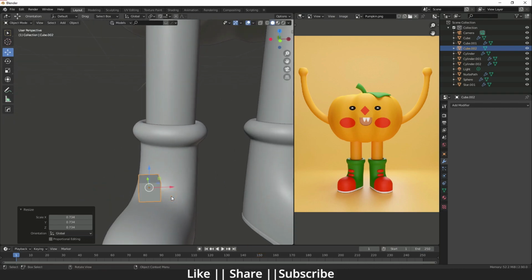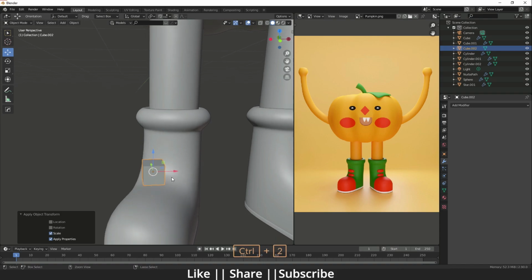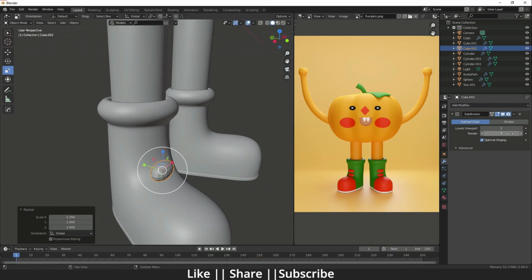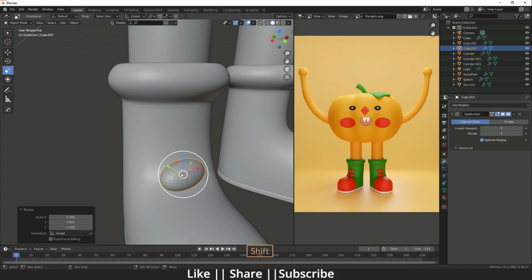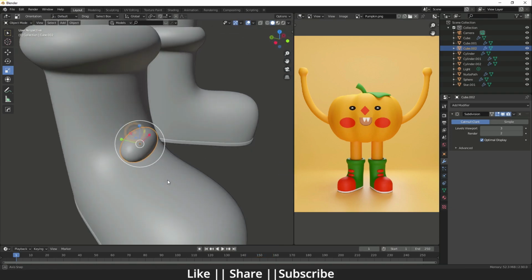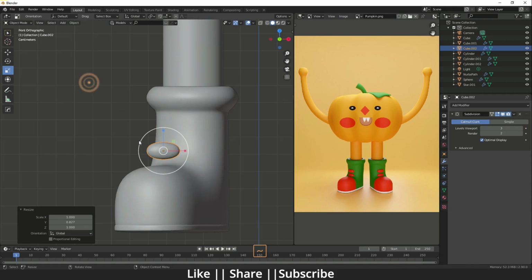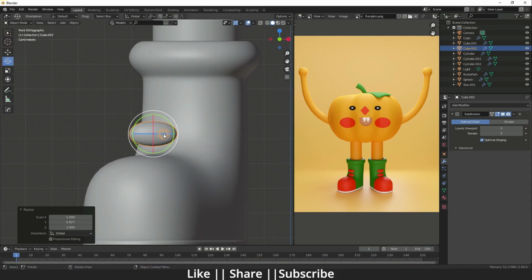Going to scale it, then I will apply the scale, then I will press Control 2 for the subdivision modifier, and then scale it. Make sure to increase the subdivision level, and just shade smooth, and just do it a little bit like this. And from the front view we can set the angle.